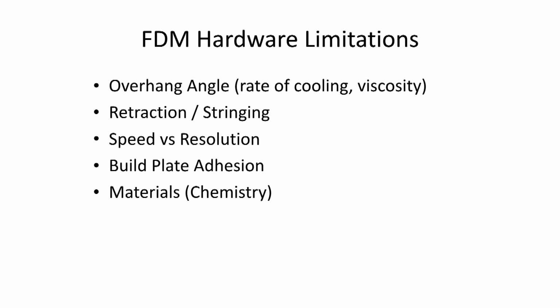And also, of course, we have a large number of limitations simply based on the materials that we can use. Here we have a thermoplast, polylactic acid, running into our machine. There are a lot of other common plastics, such as nylons or acrylonitrile butadiene styrene, ABS. We could use HIPS as well, high-impact polystyrene, which has the advantage of chemically being degradable in places where other plastics wouldn't be. So we could use that as frangibles, right, supports, things like that on our prints. But all of those share that one property, that they are thermoplasts. So with this type of machine, we have to be able to melt a material, flow it into place, and then solidify it in place. So there are a lot of materials we couldn't use.